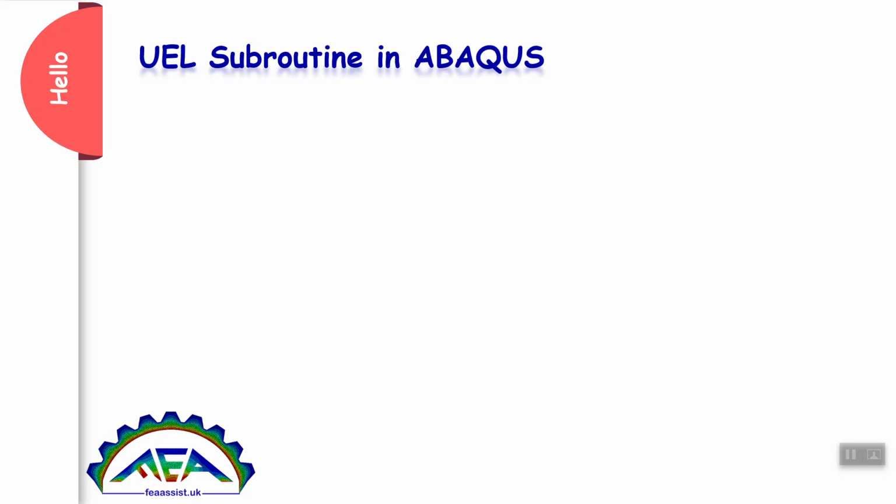Hello? You want to learn UEL subroutine in Abaqus easily and quickly. UEL is a subroutine to define a new element in Abaqus. Consider you have a one-dimensional element with points A and B. For example, temperature in this element is interpolating between the temperature of point A and temperature of point B. So, an interpolation function computes and defines the temperature in any points in this element.